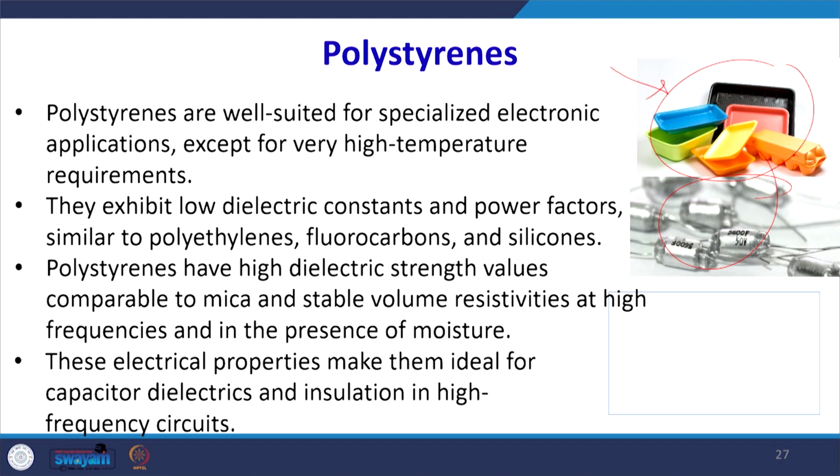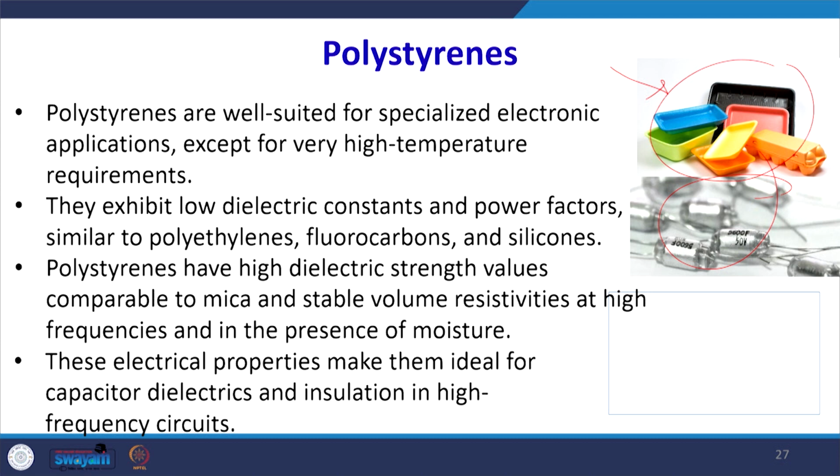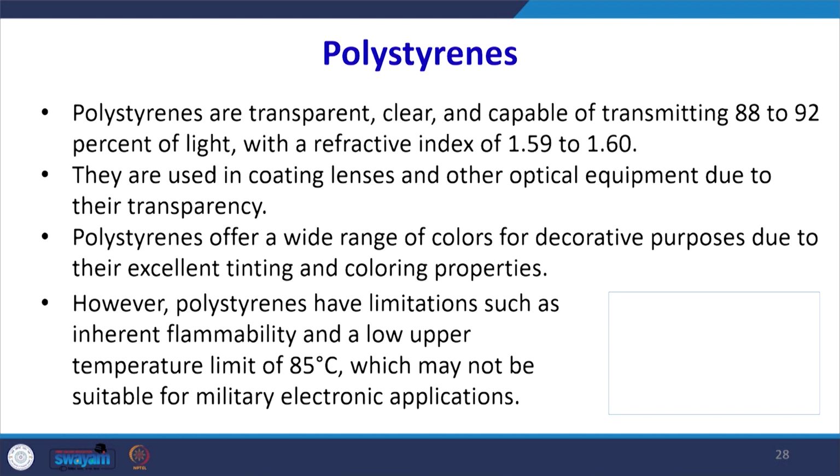So if you have a moderate temperature requirement, you can use these polystyrenes, and they exhibit low dielectric constant and power factors similar to the polyethylenes, fluorocarbons and silicones, and they have high dielectric strength values comparable to mica and stable volume resistivity at high frequencies in the presence of moisture. These electrical properties make them ideal for capacitor dielectrics and insulation in high frequency circuits.